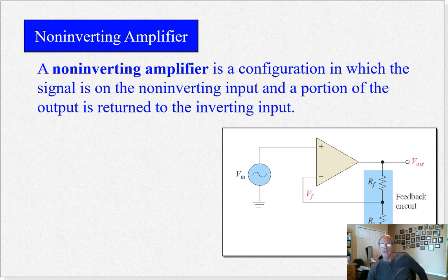So what does that mean? What that means is, since these two inputs need to be equal, or almost equal, to produce an output, when everything's stable, we basically have these two inputs that are right next to each other. They're almost the same voltage. But we have this open loop gain of, let's say, 200,000. So they're almost equal, but maybe a small voltage apart from one another.